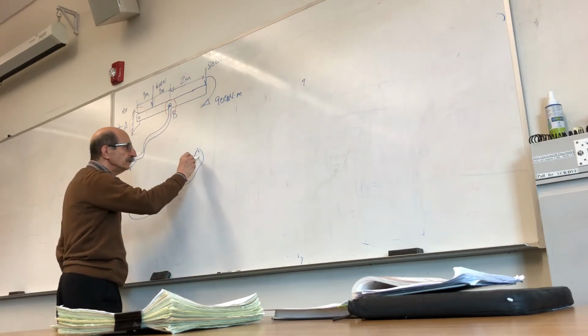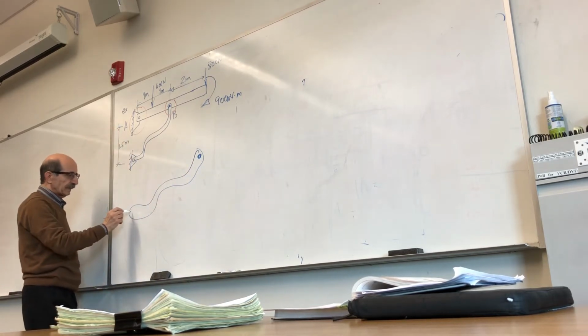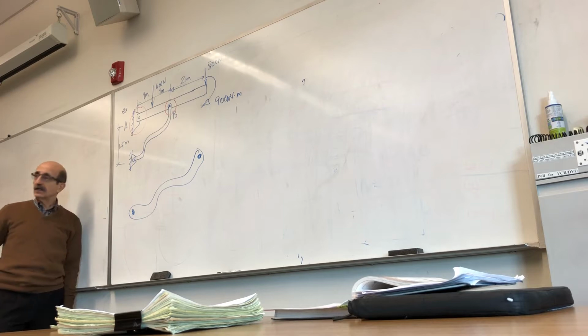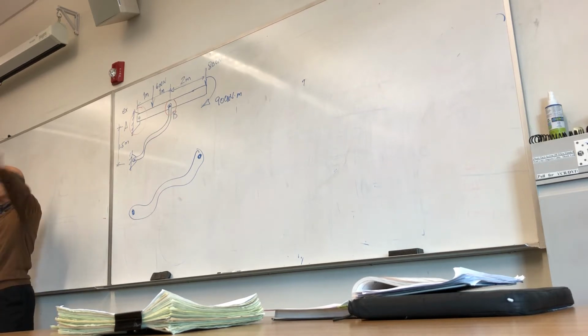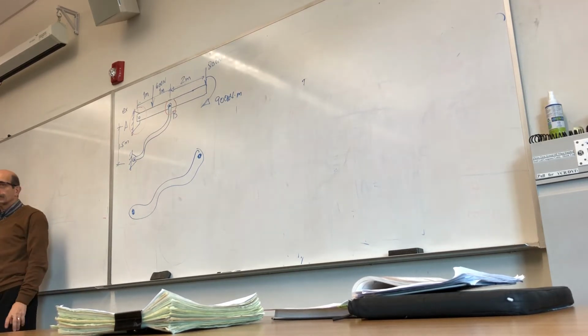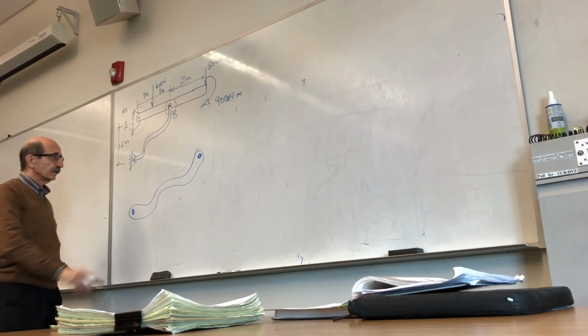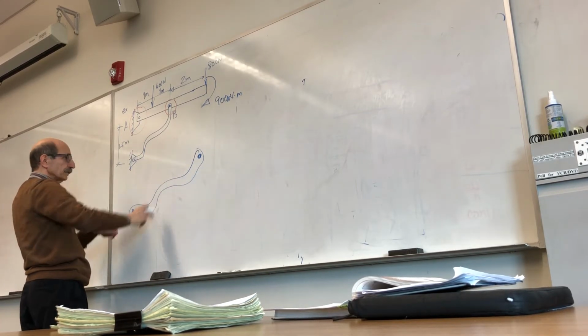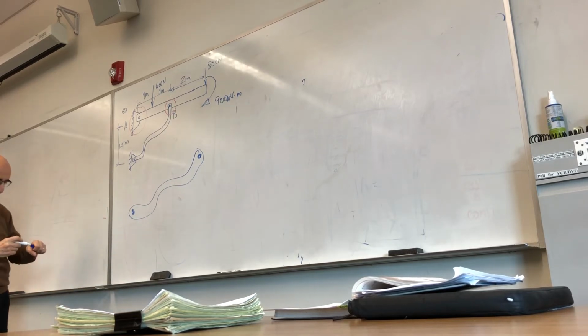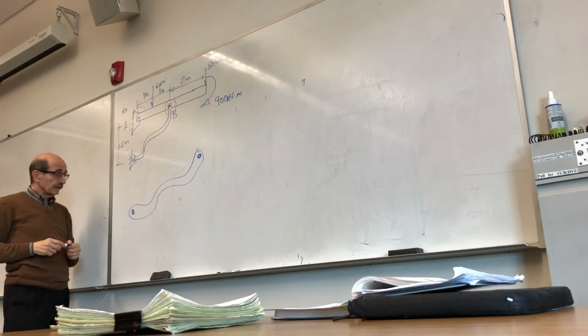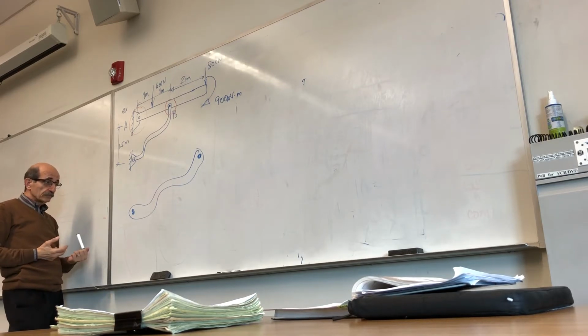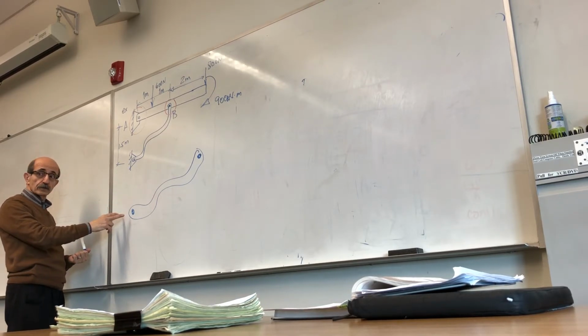It is pinned at one end, and it is pinned at another end to the rest of the world, okay? Which is what we have here. We have this weird looking piece, pin connected here and pin connected here. As we said, if these are pin connections, that means you have how many unknown forces here?